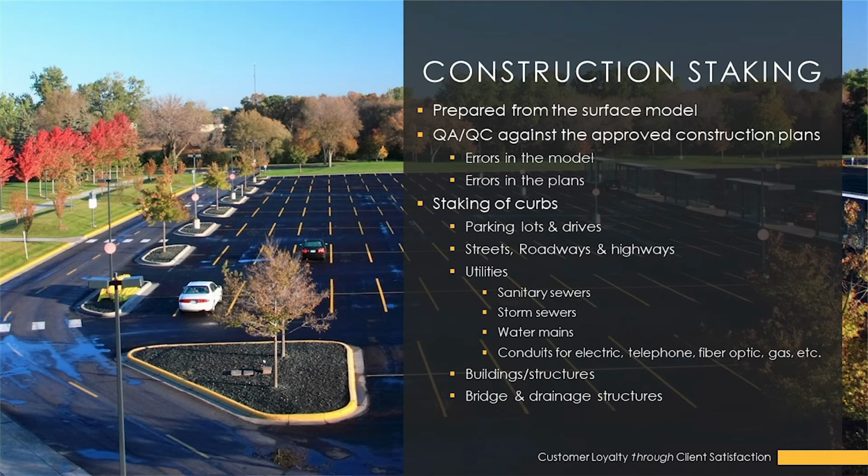The construction staking, the preparing from the surface model. We take that data, and again along with the work order and the stakeout maps, you're generating your points that the survey crew, for instance on a parking lot or your curb, you're generating those points for what we call the fine staking operations.